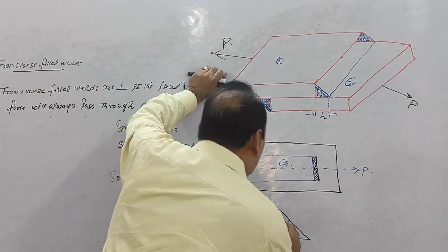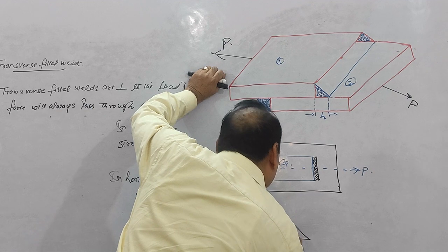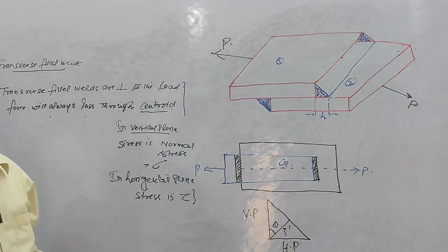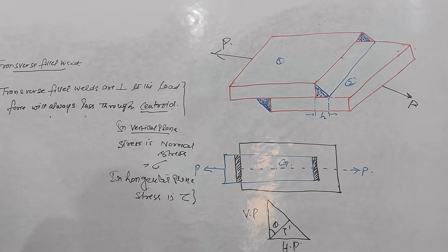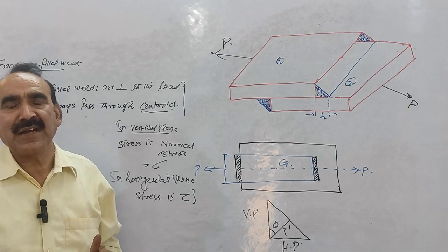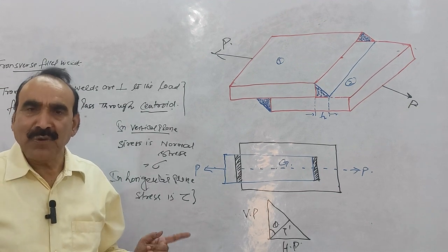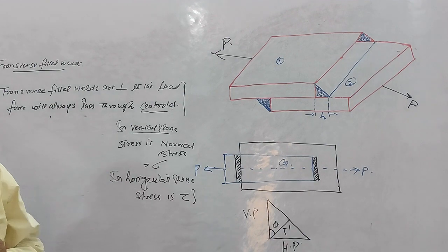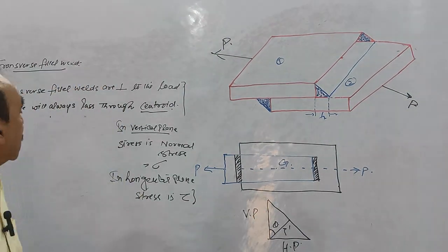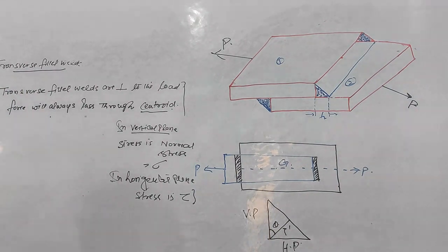And if I say that this thickness, this is your t dash, है आपकी मिनिमम थिकनेस, that is t dash, the minimum thickness. सो अगर आपकी t dash मिनिमम थिकनेस है, तो जो क्रॉस सेक्शनल एरिया होगा वो कहां पे मिनिमम होगा, इंक्लाइन प्लेन के ऊपर होगा, राइट. जो हमने कंसिडर किया है. तो मैक्सिमम स्ट्रेस वहीं पे होगी. तो कहने का मतलब ये है कि ये आपका इंक्लाइन प्लेन है, just like this,